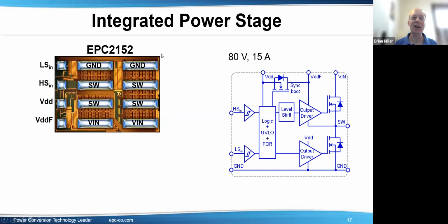The GaN FETs are very good for thermals because there's no package around them. So there's no layers of things that kind of hold in the heat. Heat can get out the bottom on these pads. You can see the pads, there's the junctions right there. There's a very close thermal route. And the backside, which is not shown, it's a silicon wafer with the GaN on top. And that's a great thermal conducting surface also. So even though the GaN is very small, there's a very good conduction path from the junction out the bottom and especially out the top.